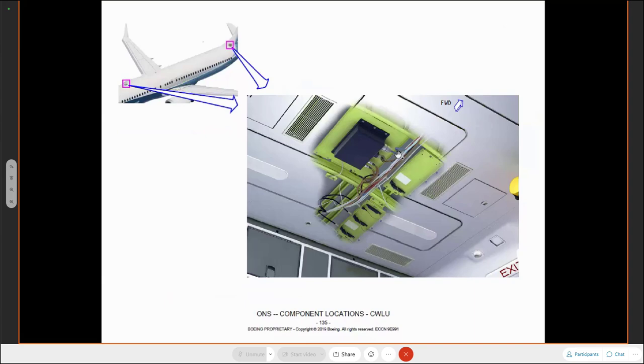And again, the crew wireless. This is something else that's optional. If you have it, you'll have two of these crew wireless LAN units, local area network units. One's forward and one aft. There's 4 antennas for each of the crew wireless units, and they allow connection to a portable maintenance device wirelessly. Again, they're an option. The network file server will provide those connections via these LAN units, and the network file server will check for security credentials for the laptops, whether you connect them hardwired or wirelessly.